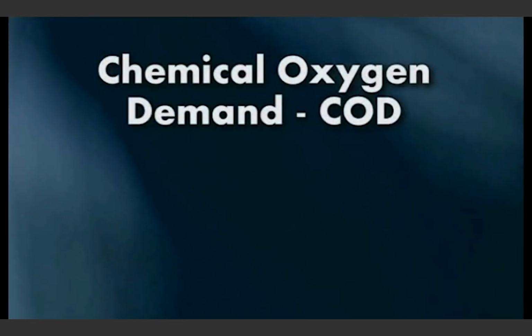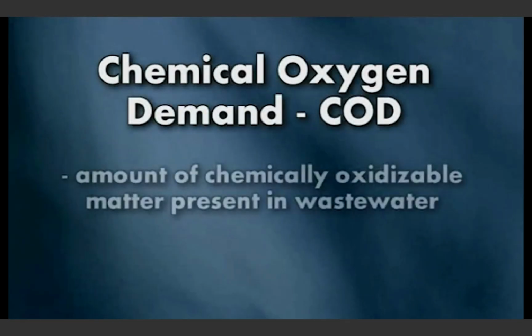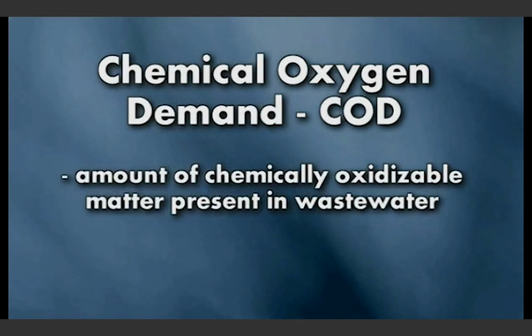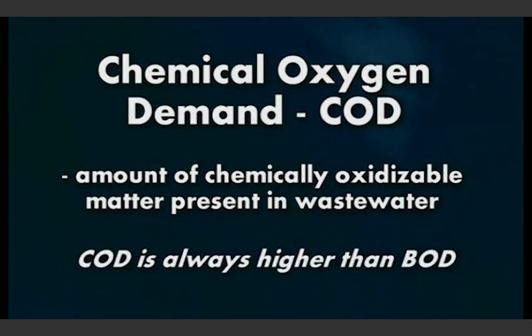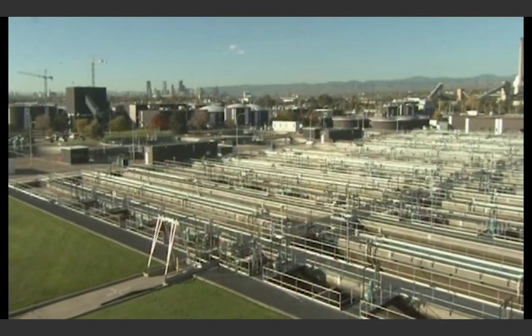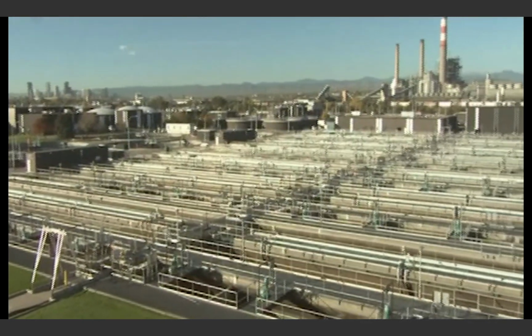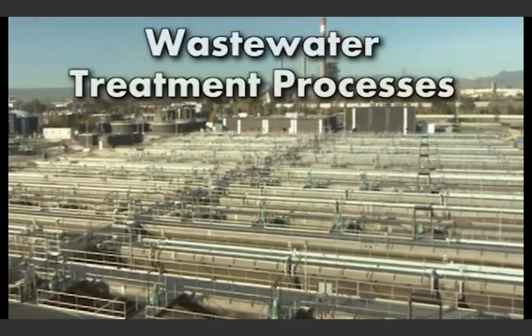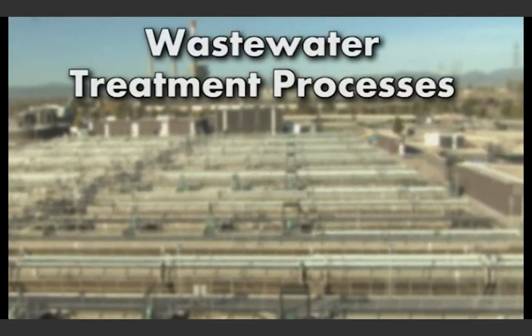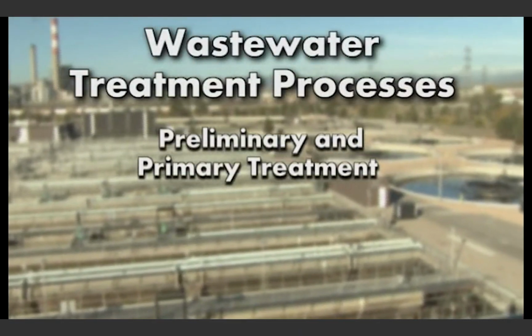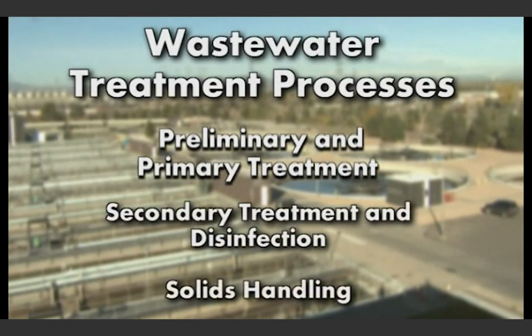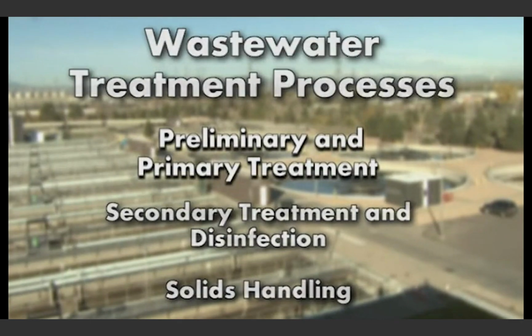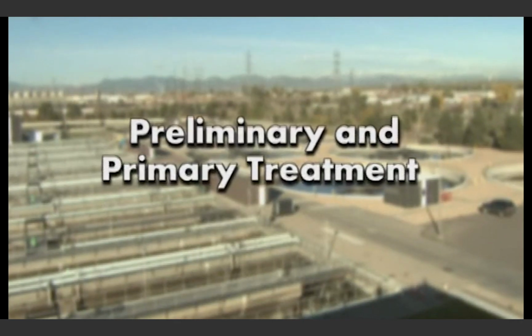The COD, or chemical oxygen demand, is the amount of chemically oxidizable matter present in wastewater. COD is always higher than BOD. The treatment processes used for wastewater can be segmented into the following categories: preliminary and primary treatment, secondary treatment and disinfection, and solids handling. This program will cover preliminary and primary treatment.